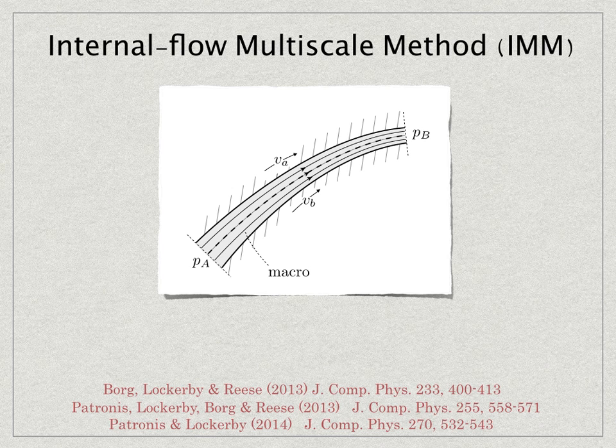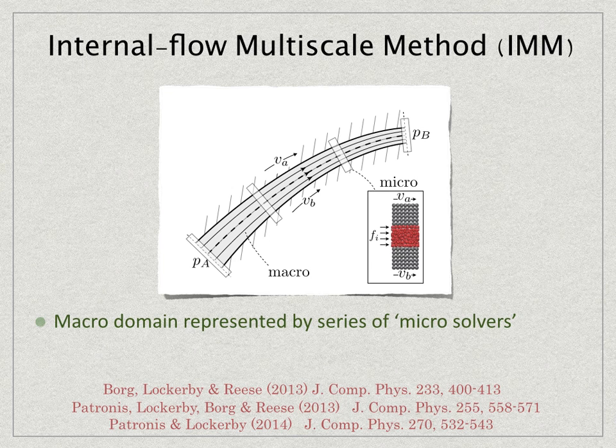So very broadly, what we do is we take a high aspect ratio, long channel flow like one depicted here, and we represent that by a series of very short molecular or particle solvers. So we reconstruct the macro field from information from these otherwise independent micro solvers. So the way that saves computational time and computational effort is because we don't have molecules throughout the length of this long channel. We just have them in these thin strips, these planes.